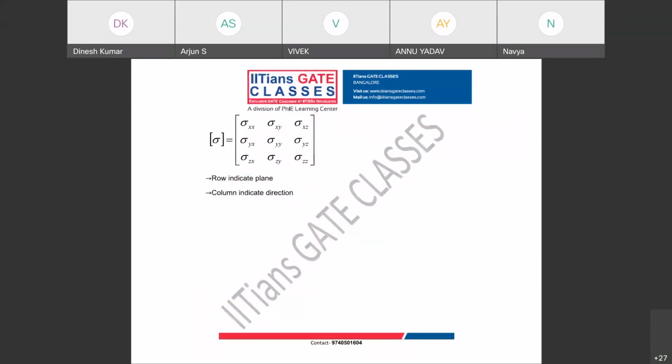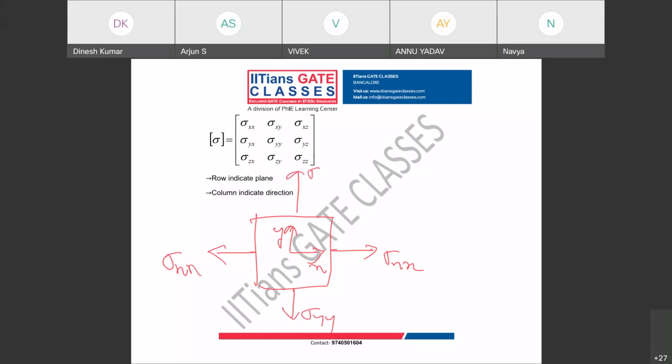Now, once you know this three-dimensional stress system, I can write the two-dimensional stress system. What is my two-dimensional stress system? Suppose you take an XY plane. How will my stresses look? There is a normal stress here, sigma XX, and this is sigma YY.